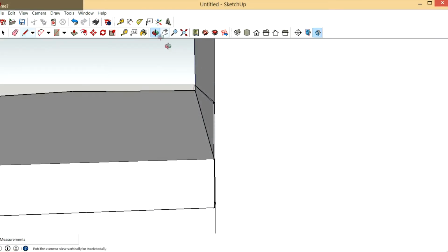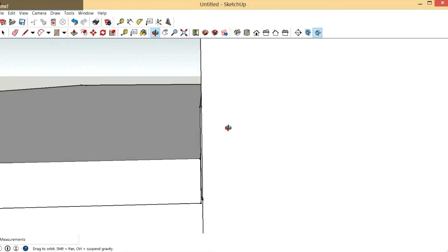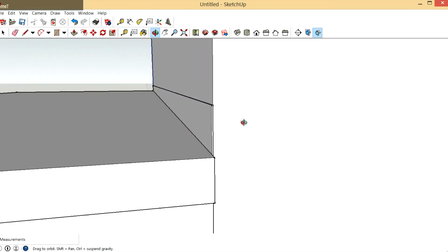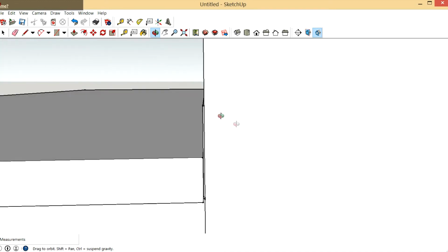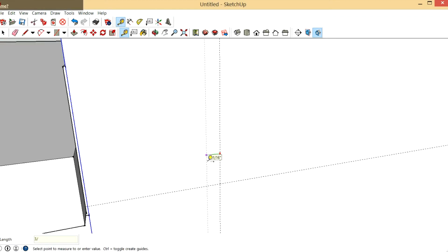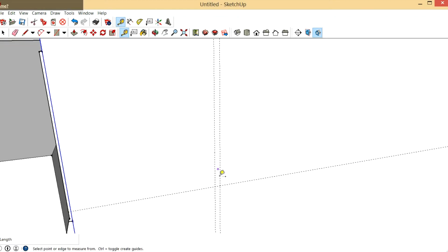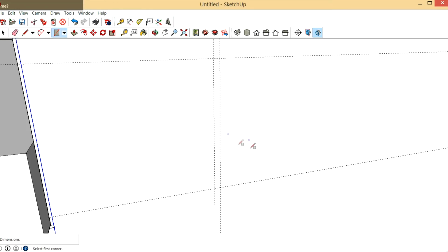Let's go ahead and make us a piece of siding to show how our siding is going to lap over our flashing, and I'll show you kind of where it needs to be in relation to the flashing. So anyway, I'm going to draw a piece of siding here. I'm going to make it 3/8 of an inch thick. I'll also make it 8 inches tall, and we'll just consider it a piece of hardy siding.